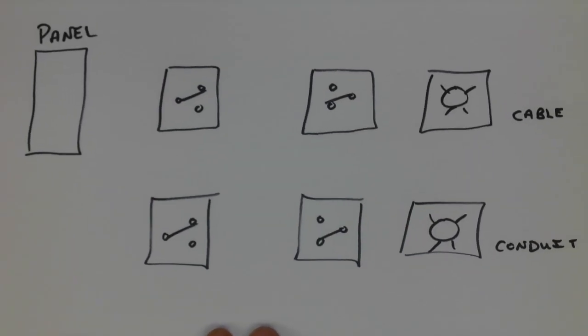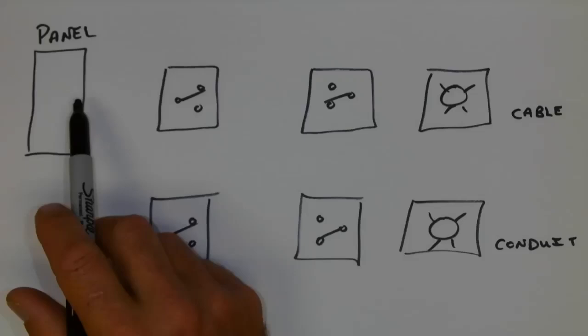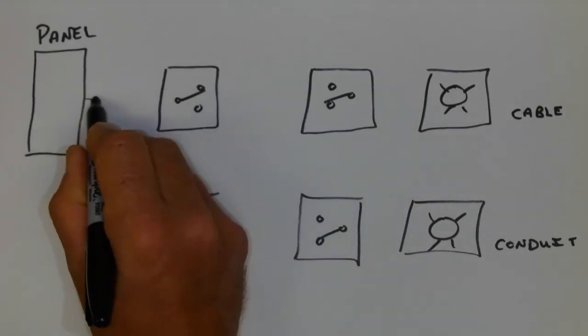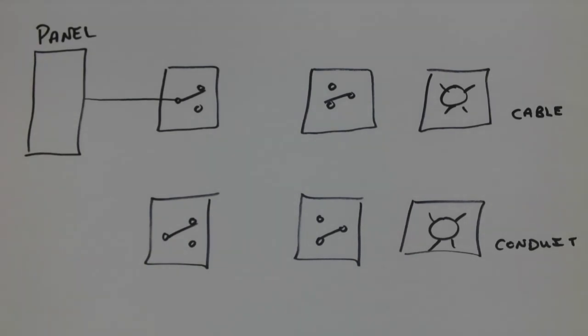Three-way wiring is the type of circuit where we have continually done incorrectly, from level 1 apprentices all the way through to seasoned journeyman electricians. If we follow the schematic, we know that there has to be a hot connection to one of the common conductors on the light switch.